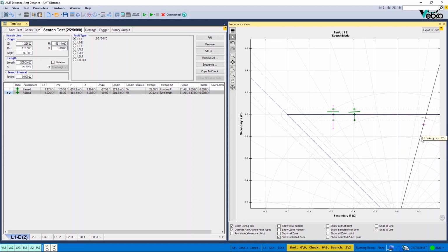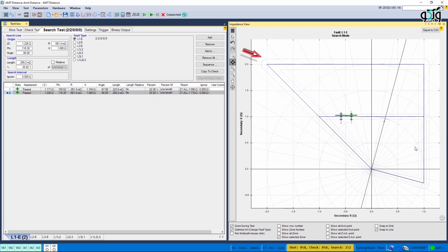About polygon or quad zone tolerances, it should be noted that the rounding off of the tolerances occurs where the zone lines intersect. The reason for this is related to the definition of tolerance. Suppose a 5% tolerance. The tolerance is the geometric location of all points which have a 5% distance from the zone line. According to this definition, the tolerances turn into a semicircle where the zone line ends. In sections where the tolerances of a zone overlap, the union of tolerances is considered as the tolerance of the zone. Therefore, based on the angle of the two intersecting sides of the zone, a part of the external tolerance zone turns into a curve.